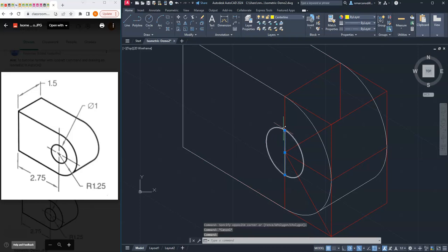This is just so we can see the short lines. I'm going to extend it, I know where I'm going, 0.25, as we know. Extend on the other side, 0.25. Then I'm going to take this and snap to the next tangent.